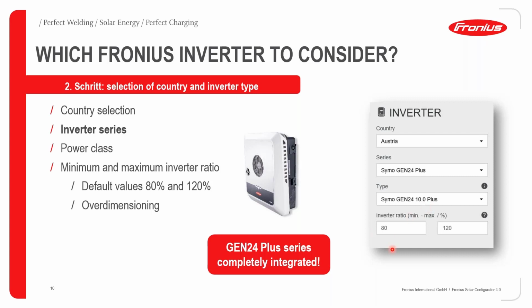And the next field, you can basically choose to dimension the inverter. So in this case, I dimensioned it at a lower limit of 80% and a maximum limit of 120%. So 80% of 10 kilowatts would be 8 kilowatts, okay? So this will basically tell the program that you want all suggestions that will at least fill 8 kilowatts of your 10 kilowatt inverter, okay?